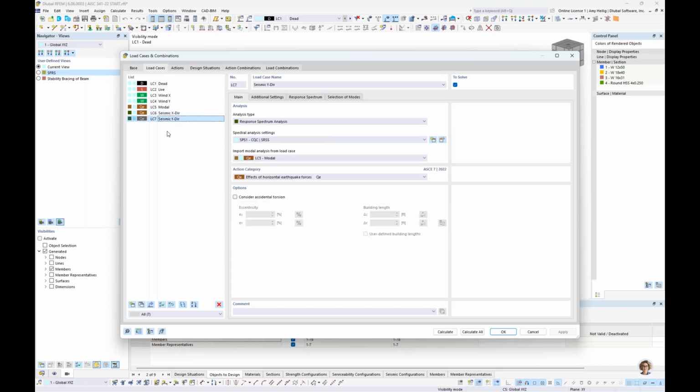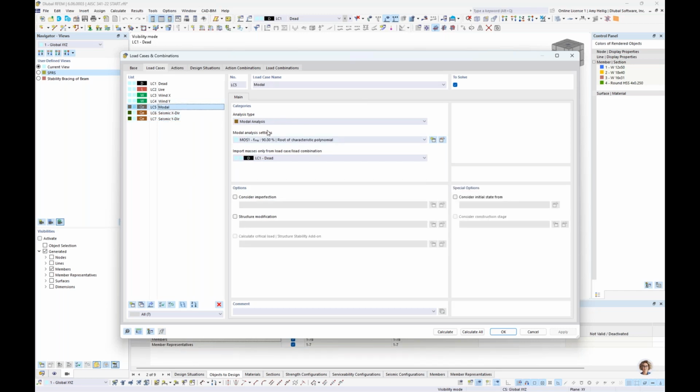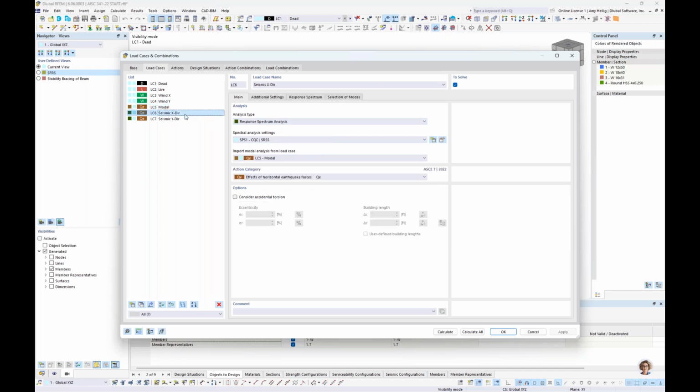Now, we definitely don't have enough time to go through this in detail, but we do have a previously recorded webinar on ASCE 7 as well as the NBC for a response spectrum analysis that you'll find also on our website and YouTube channel. But you'll see here that we do have a load case for our modal analysis, and then a separate load case is defined for our response spectrum in the X direction, as well as a separate load case here for our response spectrum in the Y direction.